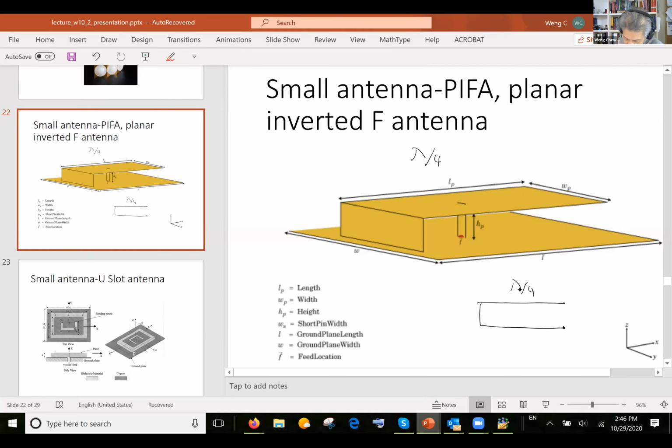So it is smaller than the other kinds of antennas, and then you can drive it with a voltage source, which is this location over here, and you can actually get this thing to be impedance matched, depending on where you put the driving source. So this is a very popular cell phone antenna because it's only a quarter wavelength long.